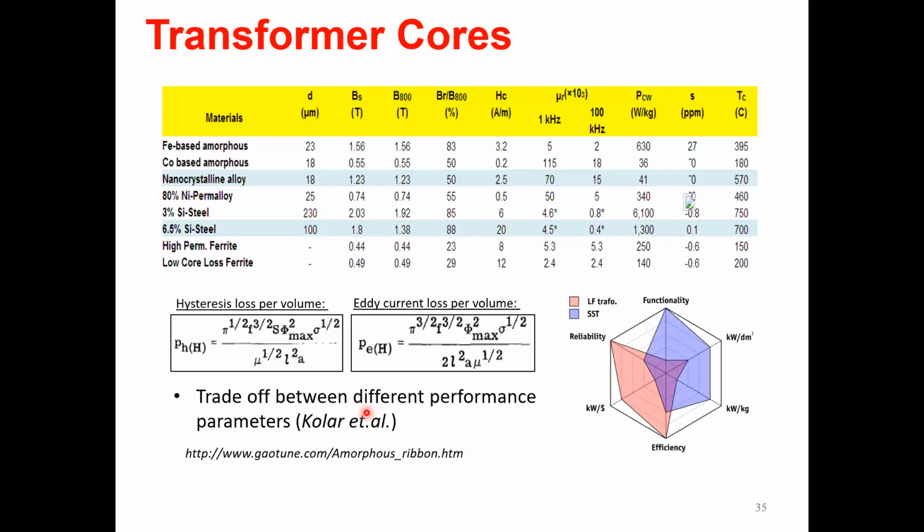What else can we do? We can go to better core materials like amorphous silicon core, which is very good. We can go with ferrite core, which is again getting popular, like what GE used. Ferrite core materials have much lower losses. But they are valuable maybe once you go towards 10 kilohertz and higher, because otherwise you don't get much size benefit from ferrite core. But once you go to 10 kilohertz and higher, the power electronics switching losses will be significantly higher, right? So there needs to be a balance between those two.